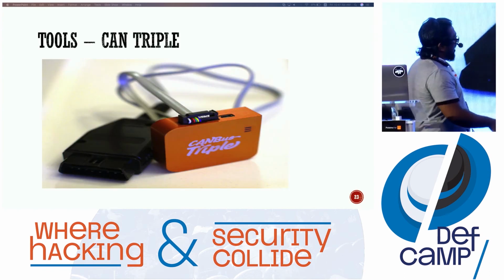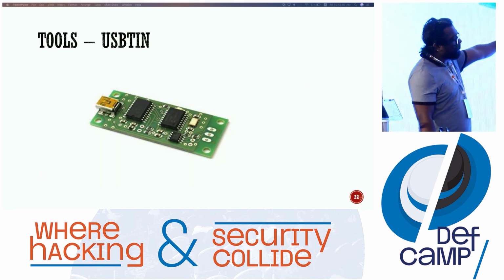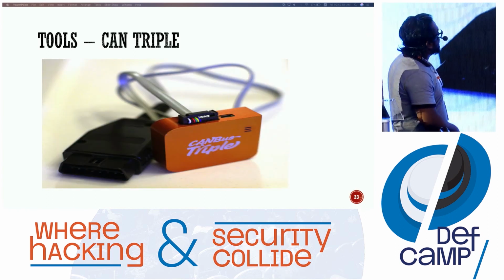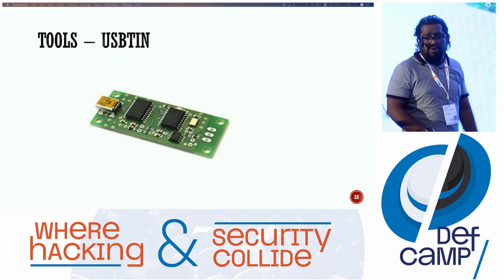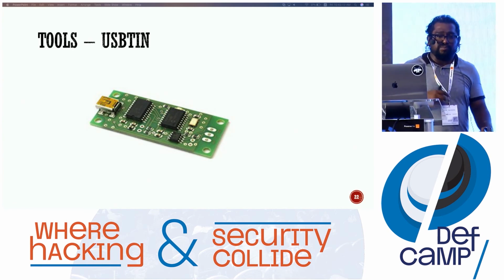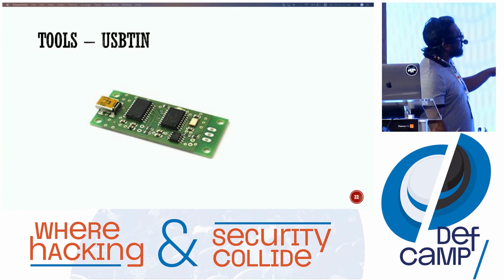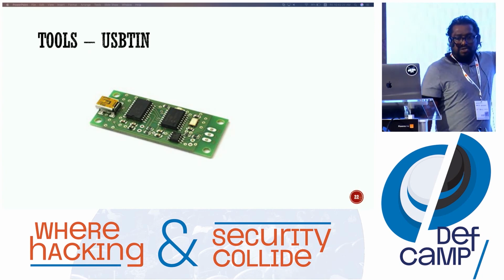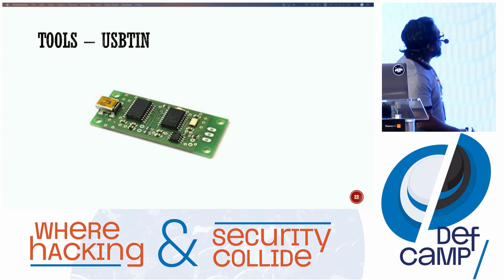Inside, they use a Microchip chipset. Even in this tool also they use Microchip. This can be used with the help of SocketCAN, right? can-utils is one of the libraries you can find on Linux. If you install can-utils, you'll definitely be able to use these things. It has a TTL to USB converter, so you can connect with Linux and start sniffing those communications as well.